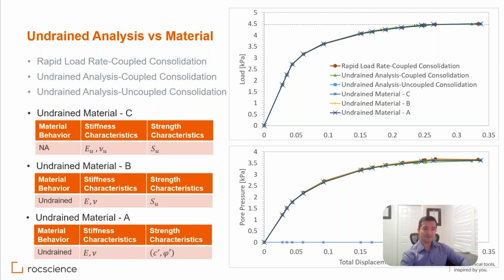I see. Excellent. The other question is, in the strip footing example that you just showed, why were you using the drained properties like C and phi for undrained analysis? Okay, so what I wanted to do in that one, I wanted to use everything in terms of effective strength characteristic, effective stiffness also. I wanted the analysis itself to handle the undrained behavior that is considered there.